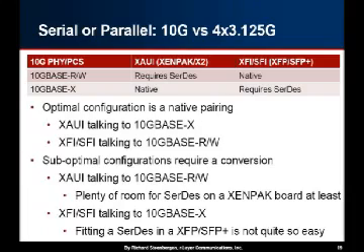So when you have, for example, XAUI, which is the older technology, talking to 10GBASE-R, you know what, if you've got a big XENPAK, there's plenty of room to fit the chip. If you've got a much smaller XFP, not so much. So that's why you tend to see very, very little in the space of going the opposite direction, but you see lots of XENPAKs that are 10GBASE-R.